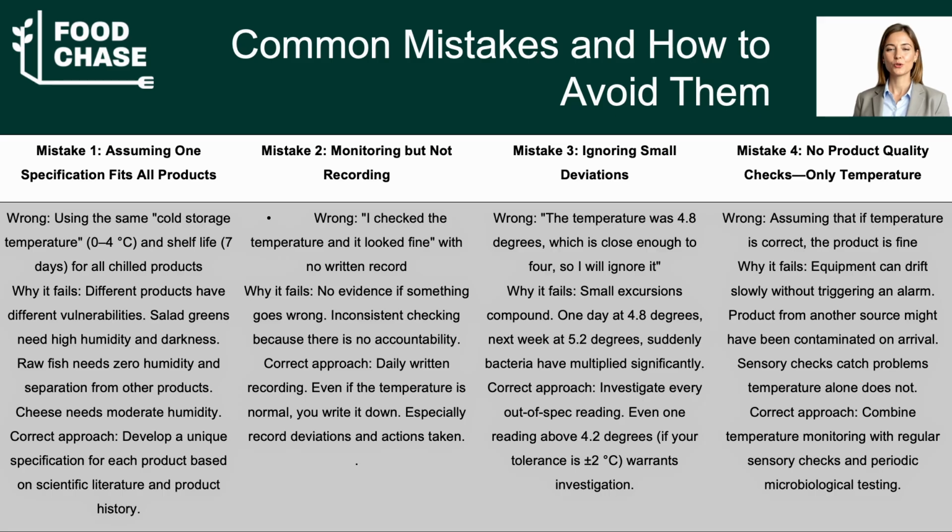I have seen cold rooms with perfect temperature records, but products that still spoil because the humidity control failed or the compressor was cycling on and off, creating condensation. Monitor temperature, but also look at the product itself. Does it smell fresh? Does it have a good color? Is it slimy? Your senses catch problems that numbers alone might miss.